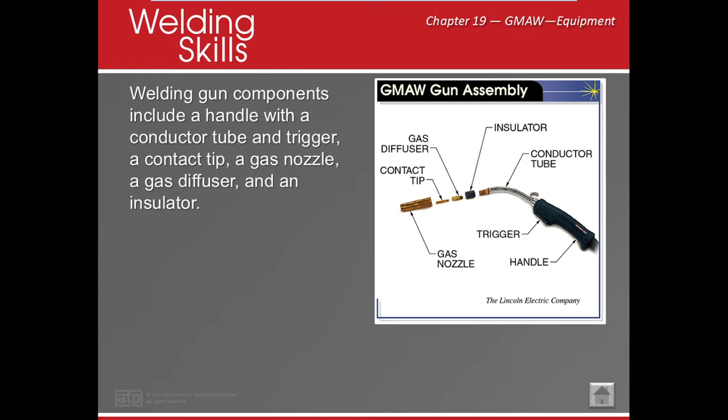All right, the gas nozzle, also called the cup, directs the gas where it needs to go. If the cup is dirty, the gas may be blocked and you end up with lack of shielding. This is bad. Also we need to remember too much gas can create turbulence and it doesn't protect you well. Not enough gas won't shield properly. So just because it's more doesn't mean it's right. We need to make sure that we have the correct amount so it works well.